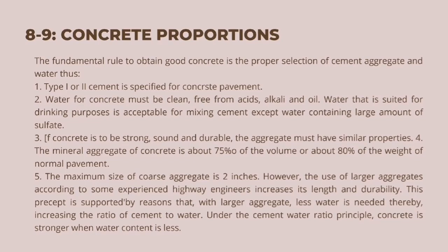3. If concrete is to be strong, sound, and durable, the aggregate must have similar properties. 4. The mineral aggregate of concrete is about 75% of the volume or about 80% of the weight of normal pavement. And lastly, the maximum size of coarse aggregate is 2 inches.